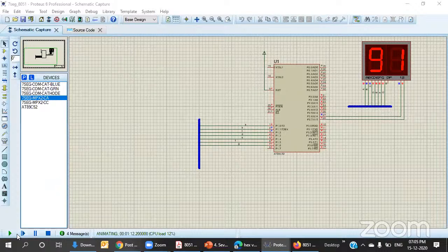If you connect any pin and I give a wrong wire label, I will show you. I'm using a wrong wire label B here, and the output is not working. So it works only with the help of wire labeling, not pins. It is based on wire labeling only. Just remember that.